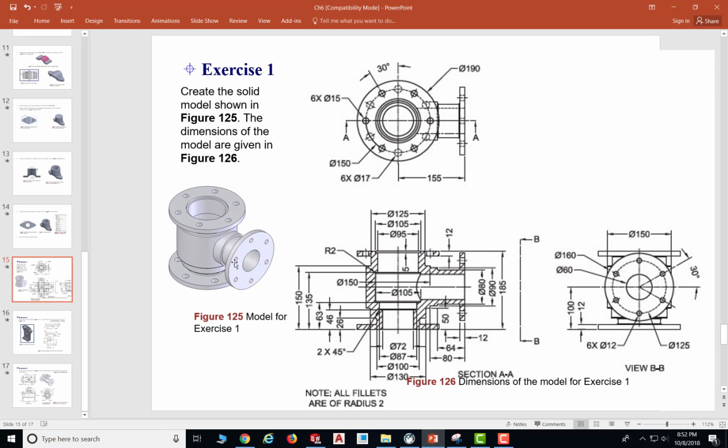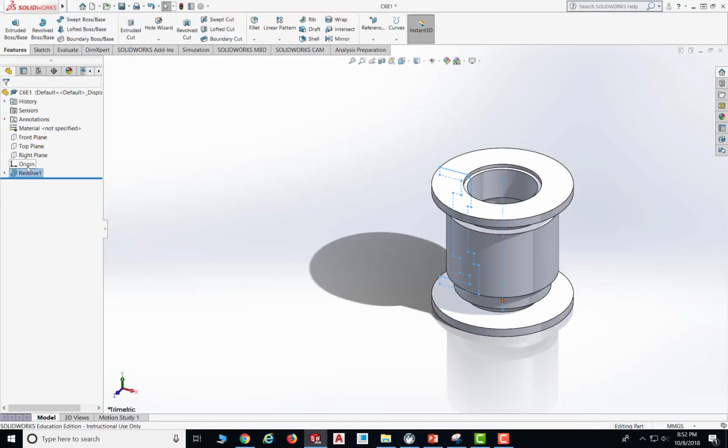Okay, the side here. Like I said, I'm going to create a new surface, and the surface I'm going to create is at 155. From the center, I'm going to use the side plane as my reference, and create another plane that is parallel, at a distance of 155. So let me go back here, put the mouse here. Yeah, it's the right plane.